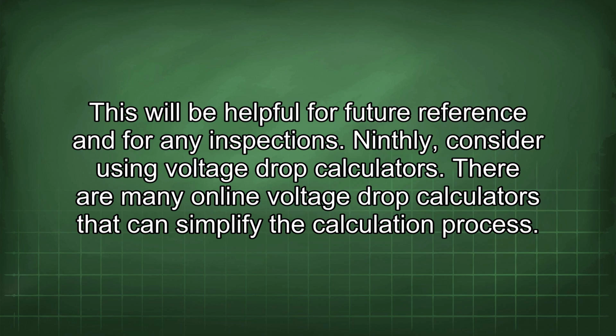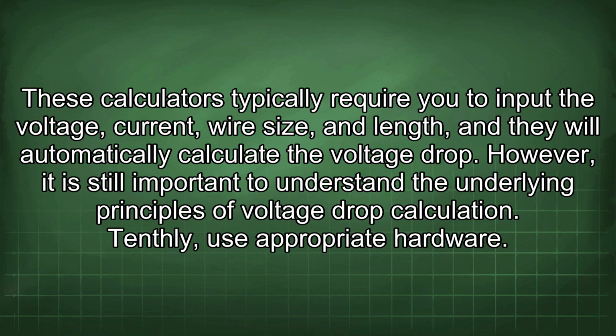Ninthly, consider using voltage drop calculators. There are many online voltage drop calculators that can simplify the calculation process. These calculators typically require you to input the voltage, current, wire size, and length, and they will automatically calculate the voltage drop. However, it is still important to understand the underlying principles of voltage drop calculation.